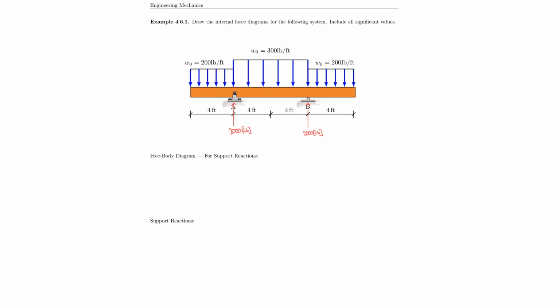And then you need to understand how to use the information from the load case to draw your diagrams. It's very unlikely that a beginner would immediately put all the pieces together when they have to apply it. So I recommend that you start making a cut at 1 foot, at 2 foot, 3 foot, 4 foot, 5 foot, 6 foot, and so on, and just do as many cuts as possible so that you can understand what is happening in the system.